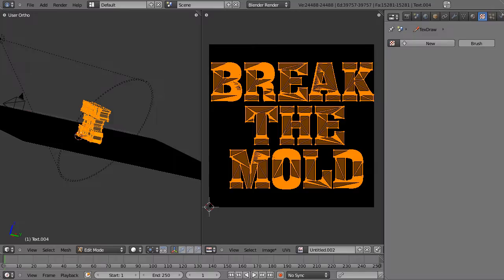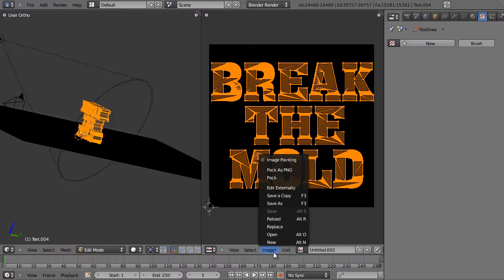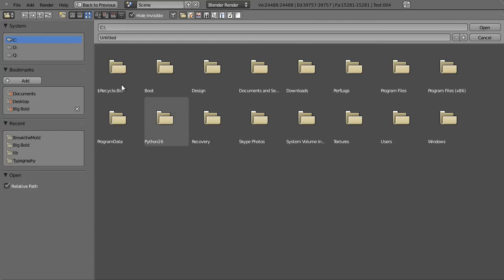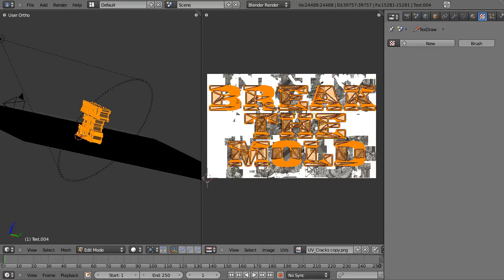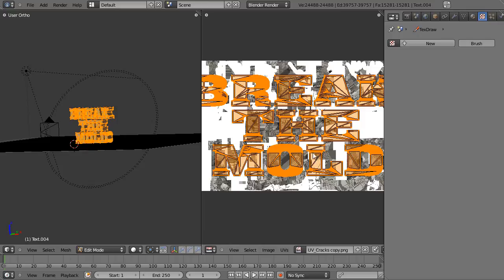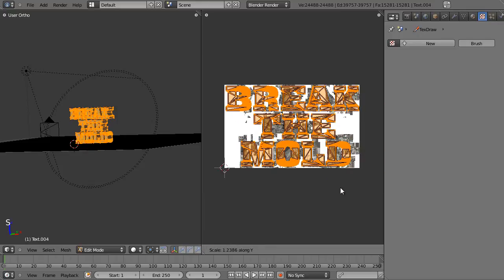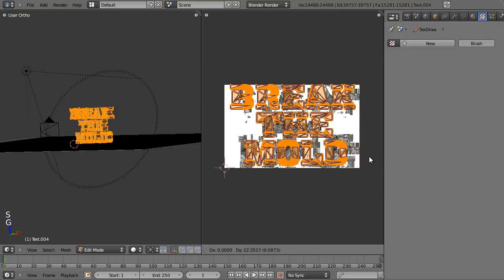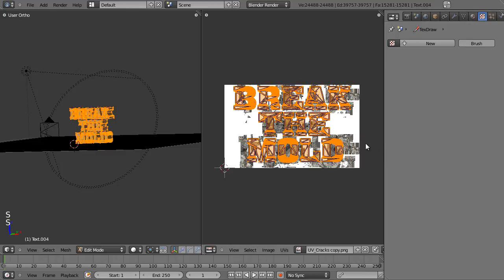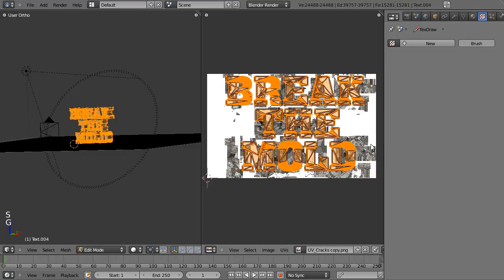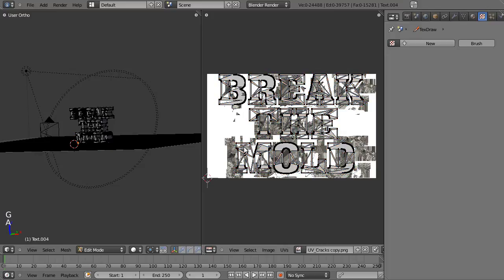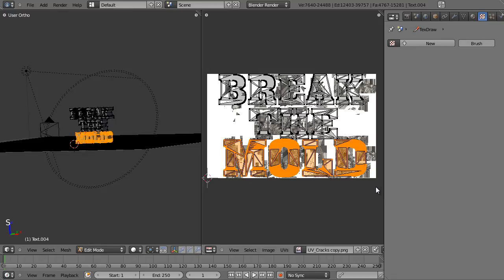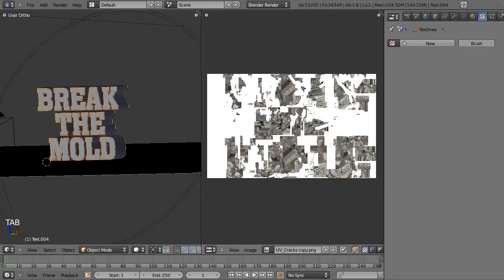Then once you've done that, go back into Blender, select Image, Open, in the UV image editor there, and then select that texture that you just created in your image editor. And if you actually did this properly, unlike what I have, then it will match up perfectly with what you've just done in the UV image editor. Mine won't, because I'm using the texture from the text that I created in the past, so it doesn't match up perfectly, but it works well enough just for this tutorial.